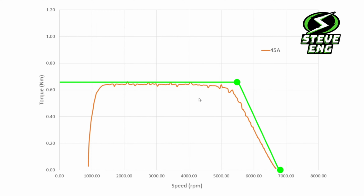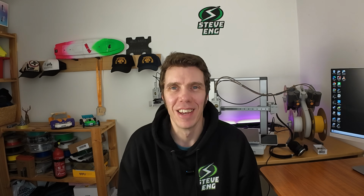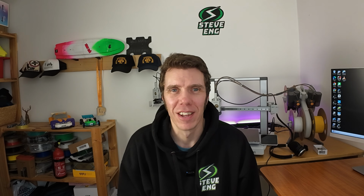Certainly good enough to use as an approximation. I mean, we're slightly above the measured data because we haven't considered factors like voltage sag, saturation or eddy current losses as measured earlier, but I think this is certainly good enough to use as an approximation to put in some other calculations going forwards to do some more estimations of our speed car performance. When I first did this, I couldn't believe how accurate the prediction could be, and I started thinking about how I can make use of it in my speed car development. Let's have a look at what I came up with.